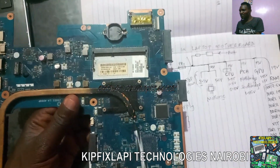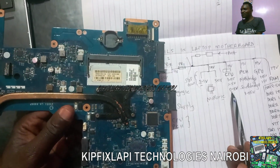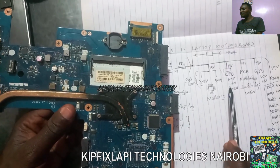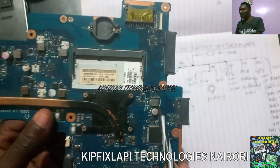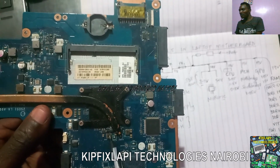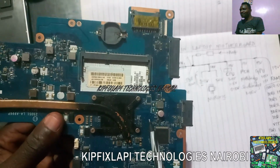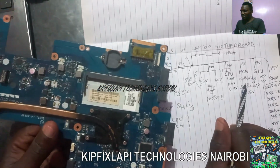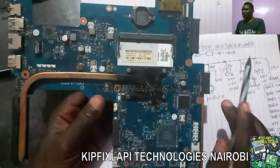So in fact, what I'm trying to say, you must have the 3 voltages. In short, for the CPU, I'll be having 3 different kinds of power circuits, right? So I have 1.05 here, 0.8 here, and 1.5 here, whichever way, right? Yes. Same case with the PCH or the north bridge. For this laptop, I believe it is integrated inside the CPU.